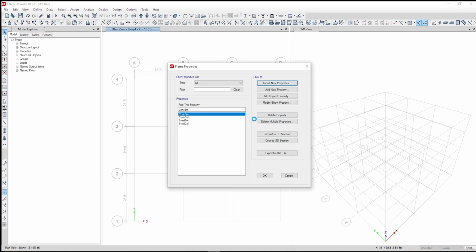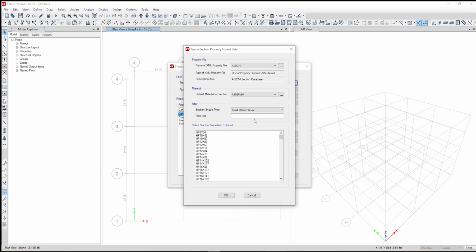In this Frame Property Shape Type window, you can define the shape and properties of your steel. Remember that we require W16 to W18 beam sizes for our auto-select list. To choose W16 through W18 sizes, left-click on W16, scroll down to W18, hold the Shift key on your keyboard and left-click on W18.